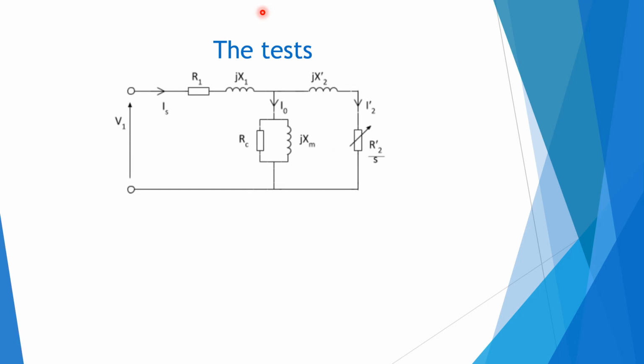So we first get the equivalent circuit, because then it's easier to understand. The first is the blocked rotor. As the name suggests, you simply block the rotor from moving. So now the slip is permanently 1. Right. This means that, just like in the case of the transformer, since these are much smaller than the magnetizing branch impedance, this is so large that very small current is flowing through here and we ignore it.